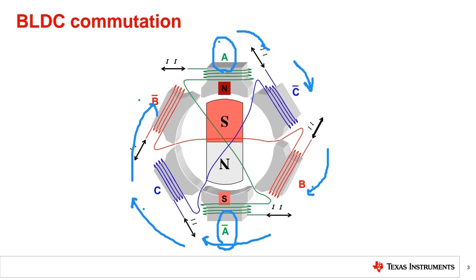However, in the brushless DC motor, the commutation needs to be decided by the motor driver circuitry using feedback of position from the motor. The feedback mechanism will be covered today and next class. What is the position feedback? If you want to commutate a brushless DC motor, you need position information. Every 60 degrees, you need to detect the position of your brushless DC motor. How can you achieve it?